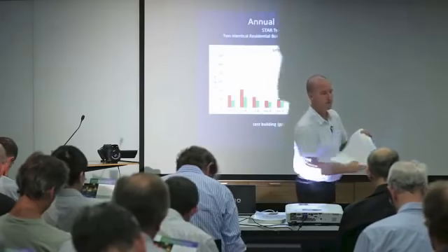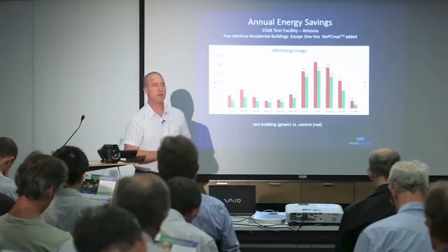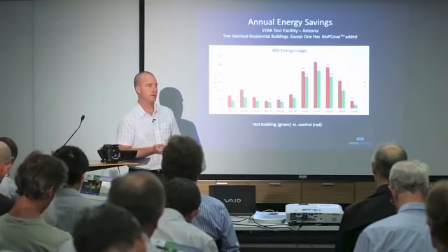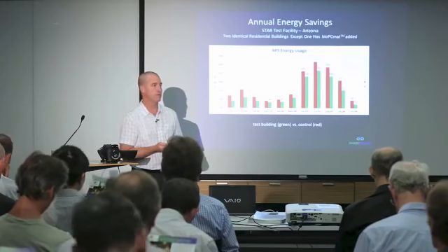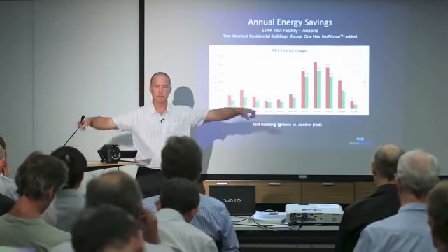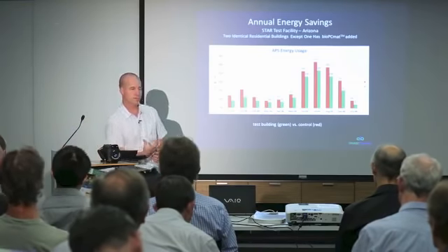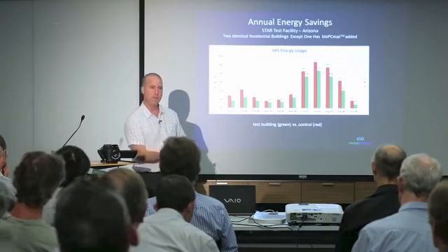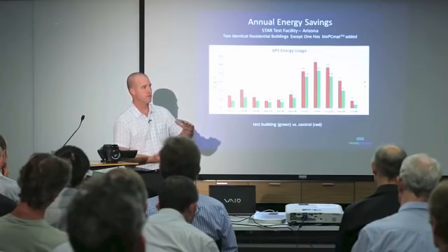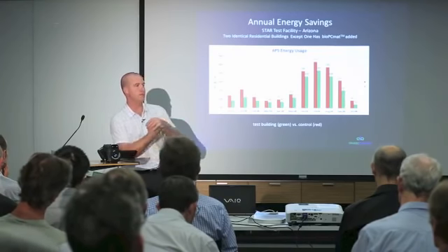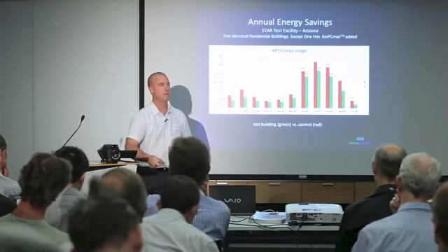If you look at that material, at the very bottom it tells you it's 0.085 kilowatt-hours per square metre. So if you have, let's say, 100 square metres of this product, 100 times 0.085 is 8.5 kilowatt hours worth of thermal inertia. So a 10 by 10 metre square, from this wall to here and out to there. If I put a 2000 watt electric heater on in this room, it would take about 5 hours for this room to get above 25 degrees because it would keep absorbing the heat that you were delivering to the room. If I put it on 1000, it'll last 10 hours.